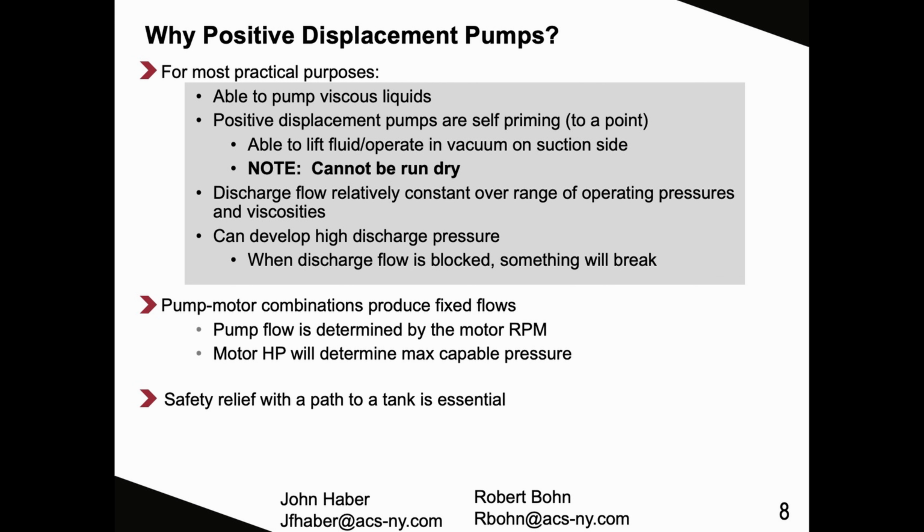Right, and a code requirement in New York City is to have a safety relief valve piped back to the oil tank between any pump discharge and a shutoff valve. Right, right. And it's a code requirement to have the positive displacement pump for the New York City market as well as international code, I think. Also, you cannot run these pumps dry. They are steel and will melt.